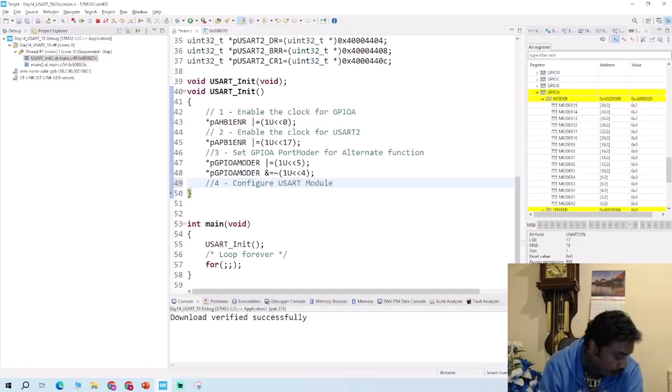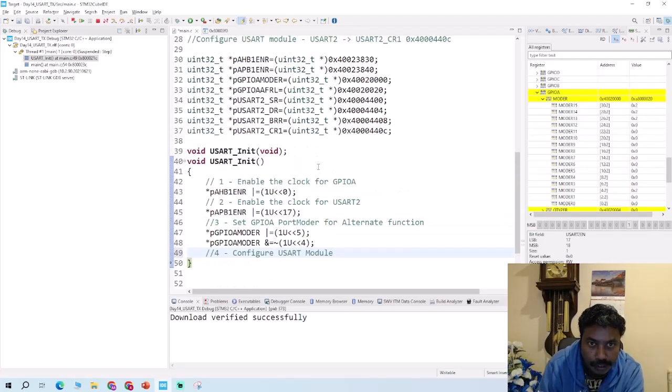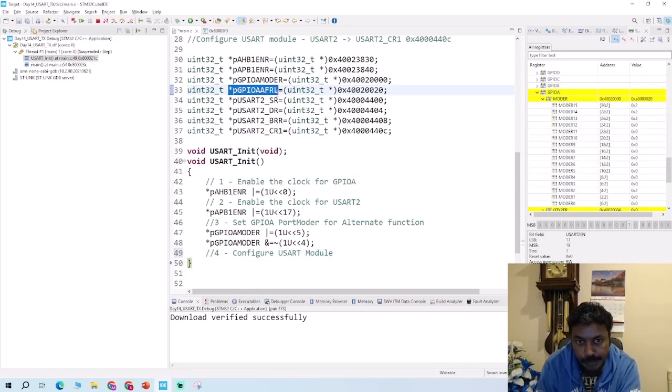To do that, you have to start with the alternate function, and you're going to enable those three as you learned earlier. We are now setting this bit, telling it what type we're going to use. Remember, we used 0111 in the alternate function register low.